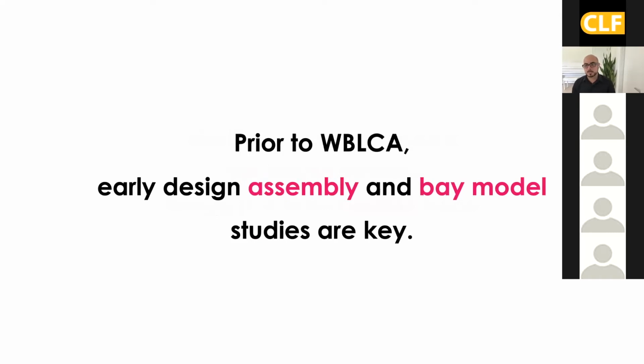When we get started, prior to doing a whole building LCA, which is what LEED would require, it's really effective to do early design assembly or bay model studies. Whole building LCAs give you the larger image, but you could always do a smaller study and multiply it by area, or just understand the effectiveness of one material or one assembly. And usually by the time that your, let's say, Revit model or building is to the point where you could do a whole building LCA, it might be too late to do optimizations of assemblies. So start early with smaller models.